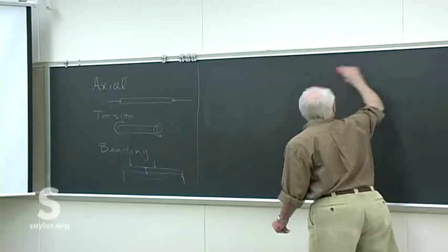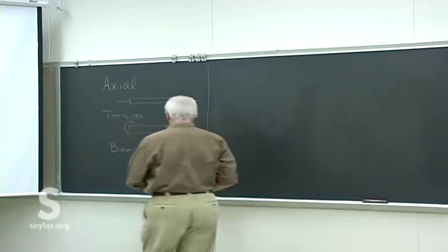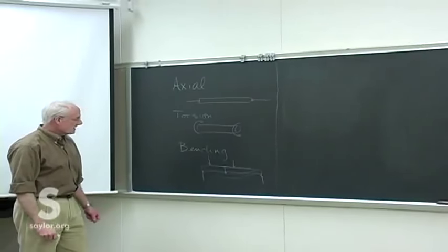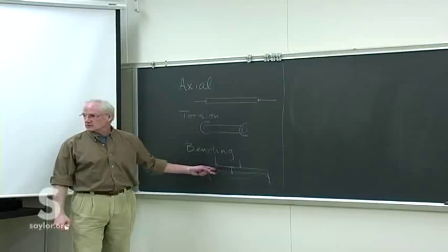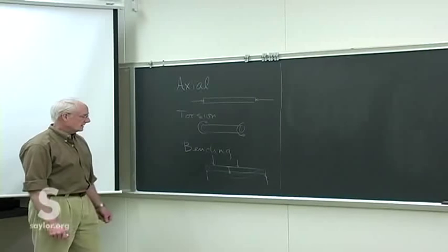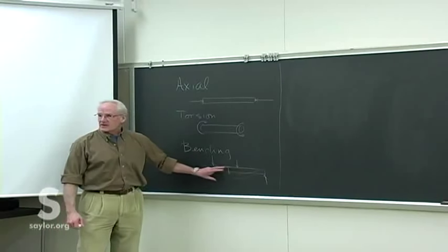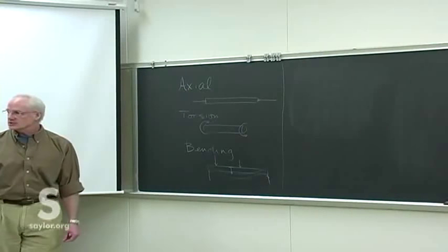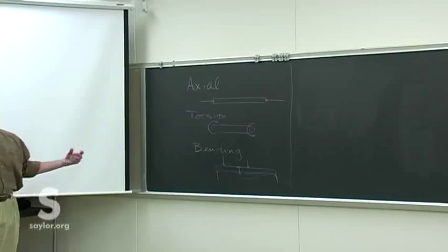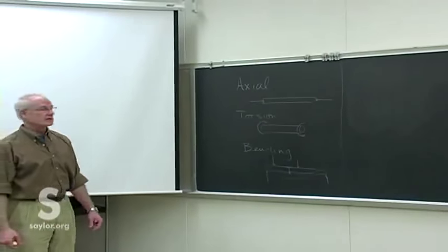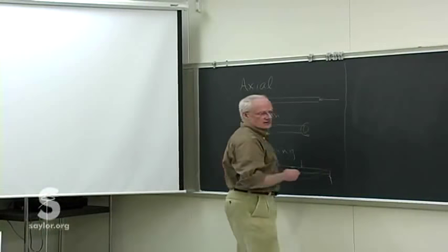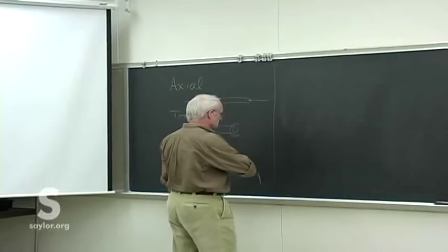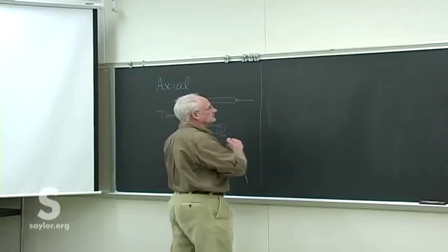Well, one of the things we're looking for the most is not necessarily the internal shear and moment at any one place, but where it's a maximum, because we could certainly come up with the ability to design beams that can withstand the maximum moment, the maximum shear at a certain place. Maybe we don't need quite so much beam somewhere else. And that would allow us to save some on some of these beam designs that we're going to be working on now.